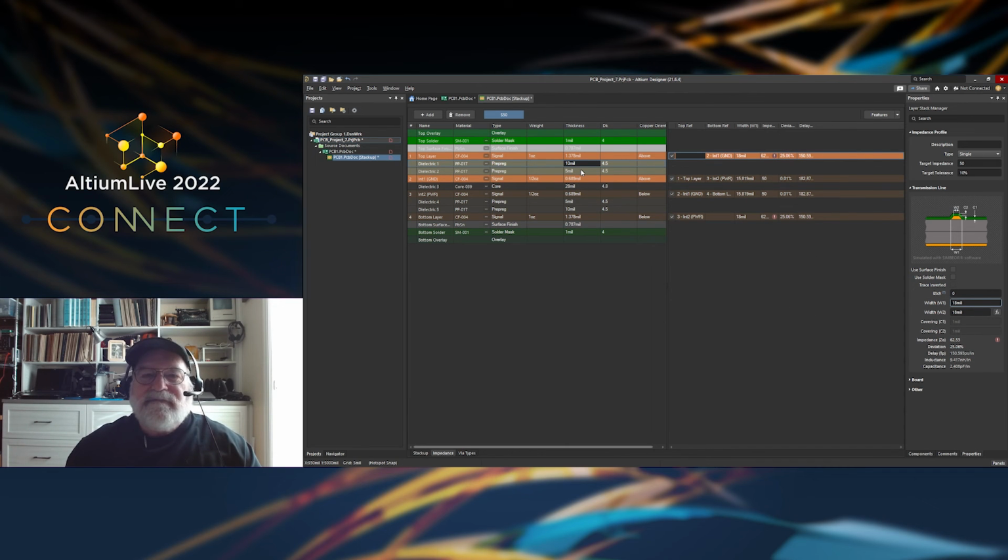Very consistent. And then dielectric constant. So we'll go back to 5 mils over here. And now, if I use a higher dielectric constant, the impedance should go down. So let's use 5 for one of these layers, and let's see the impact on the characteristic impedance. It should go down. And it did, not by a whole lot, a little bit. Didn't make much of a change, and it was only in one of these layers. And so using mixed dielectrics is easy with the 2D field solver.